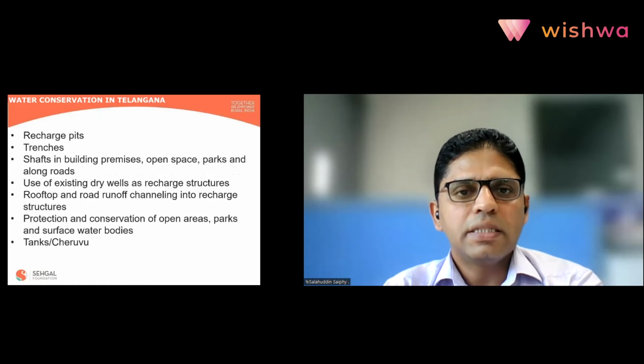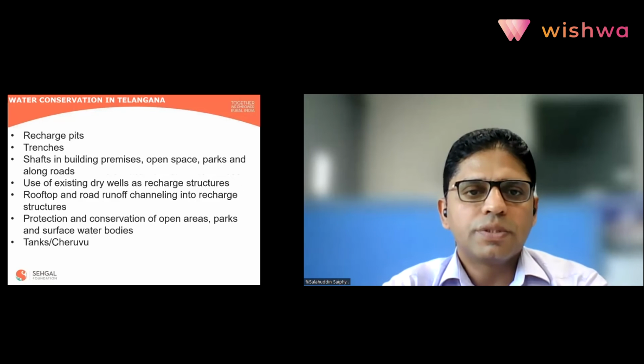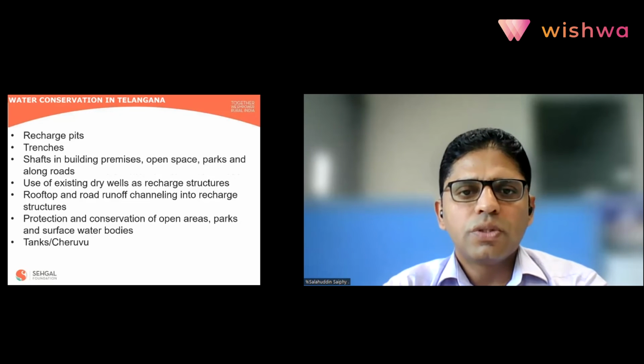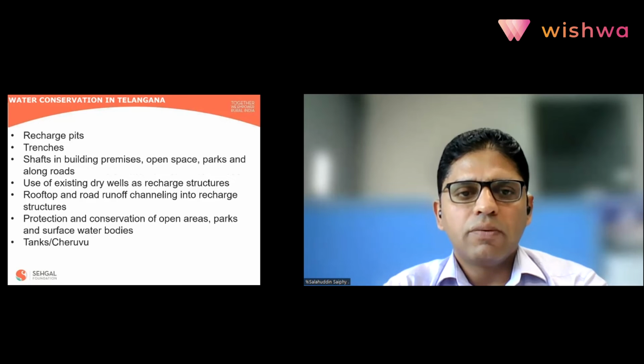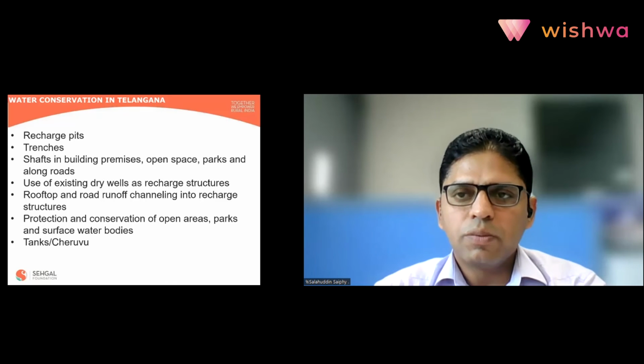Recharge pits, trenches, shafts in building premises, open spaces, parks, and roads. You can also use dry or abandoned bore wells, dug wells, or tube wells for converting them into recharge structures. And you can divert all your rooftop water or runoff water into recharge structures. And definitely you need to take care of the open areas, parks, and surface water bodies so that they are able to recharge a lot of water during the rainy season.